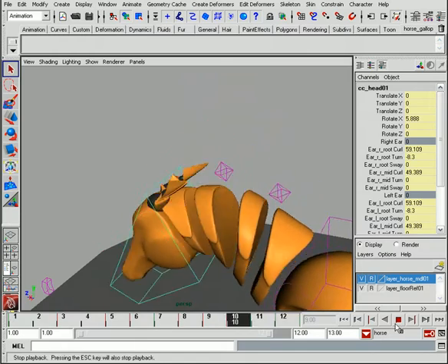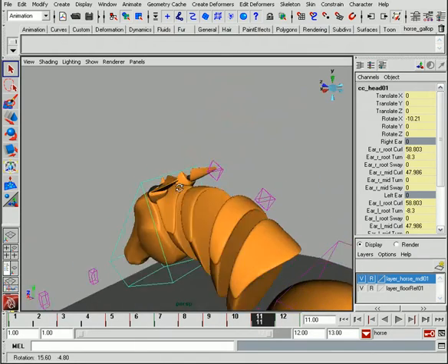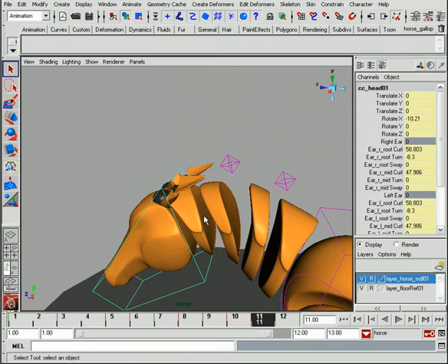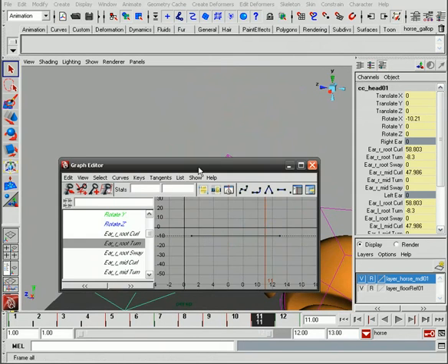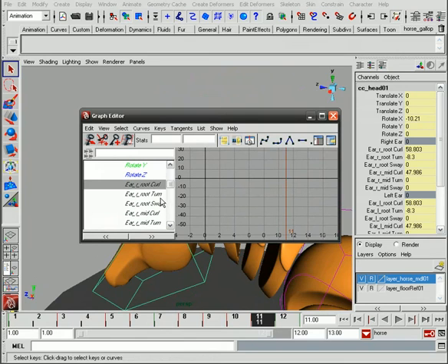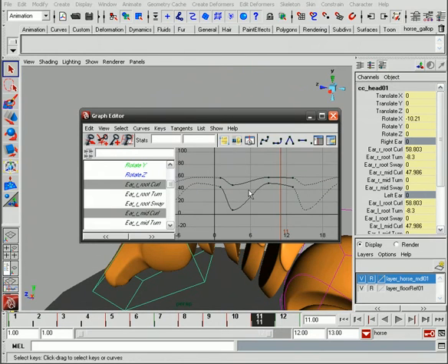So we need to offset our animation slightly so we can remove that. Okay, so what we'll do is, let's say we take our information from our right ear, we'll go to the curl, and we'll go to the mid, the curl for the root and the curl for the mid. We don't need to get our turn since it's just one pose. And we'll hit F, and let's say we have the movement of the right ear happen a little bit before the left ear. So let's say we hold shift, middle mouse button, click and drag so that we move one frame over to the left. Let's see what that gives us.